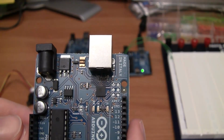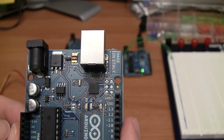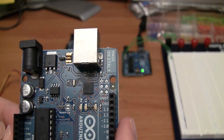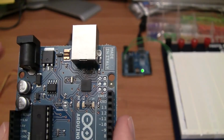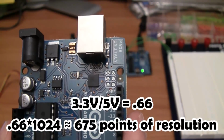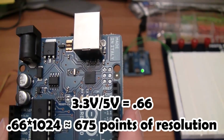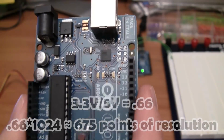You might want to consider using an external analog reference if you're only using sensors that go from 0 to 3.3 volts on a 5 volt Arduino. The reason for this is that the values from 3.3 volts up to 5 volts, if you use the default 5 volt reference, will basically be excluded and you'll be getting less resolution than you potentially could. Using an external voltage reference allows you to eliminate that problem.